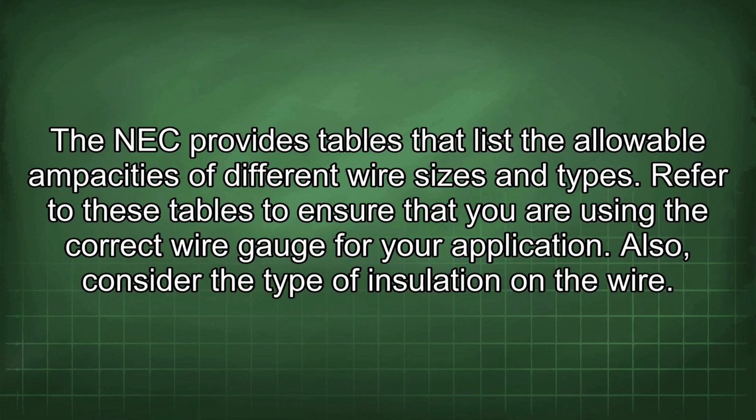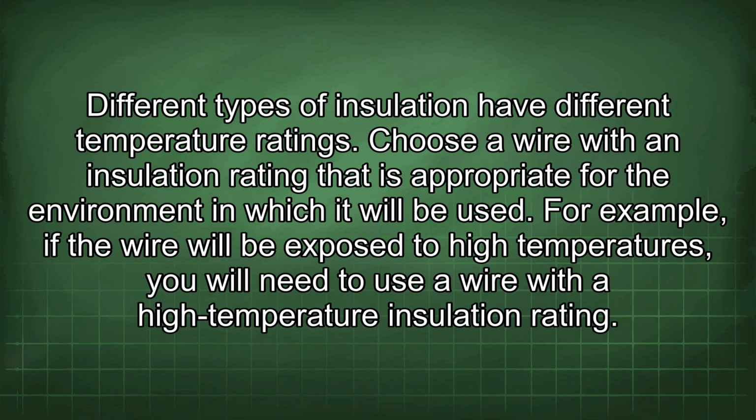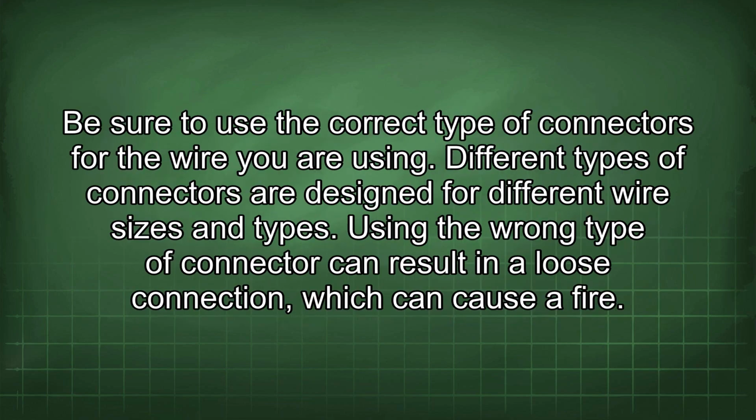Also, consider the type of insulation on the wire. Different types of insulation have different temperature ratings. Choose a wire with an insulation rating that is appropriate for the environment in which it will be used. For example, if the wire will be exposed to high temperatures, you will need to use a wire with a high temperature insulation rating. Be sure to use the correct type of connectors for the wire you are using.